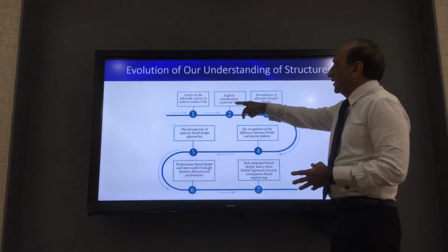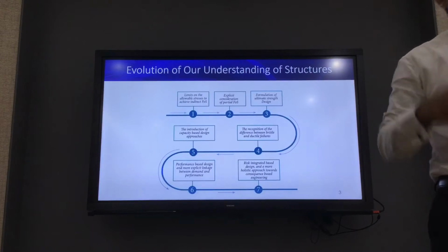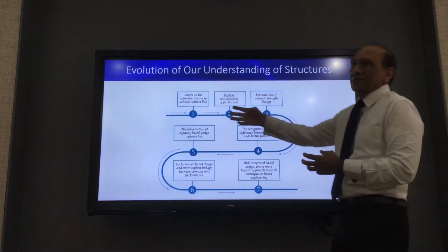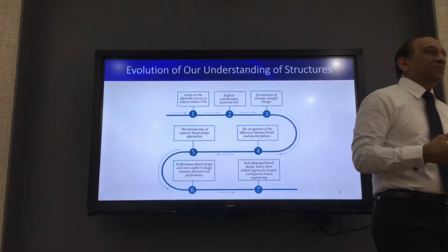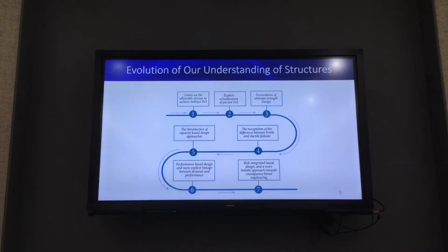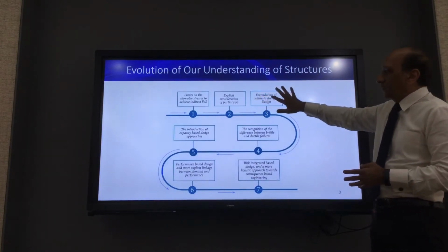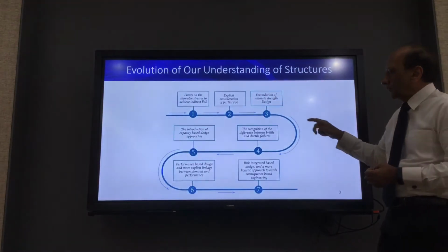And then after that, more explicit factor of safety came in, which applied to loading, applied to materials, applied to different type of action. So a lot of capacity factors come in, not only working stress on the material. So this complicated explicit factor of safety has become so complicated now that in the building codes there are many factors, especially Eurocode and other codes. They have so many factors that you need to multiply before you get the design done. And then ultimate design was formulated based on that, and now it has been becoming more and more complicated because more and more factors are coming in. I will talk a little bit more about that.